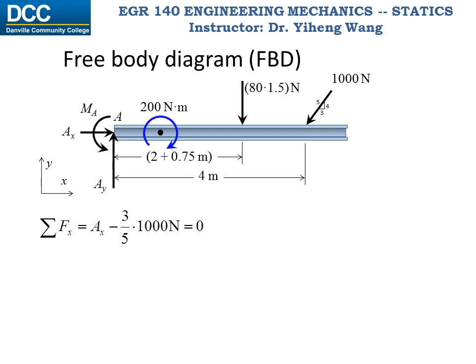Therefore, the resultant force along the y-axis equals unknown force Ay minus the resultant force of the distributed load, 80 times 1.5, and then minus the vertical component of the 1000 Newton force, and it equals 0. Again, the signs of the forces are consistent with the coordinate system I set up. Lastly, we write the resultant moment equation.